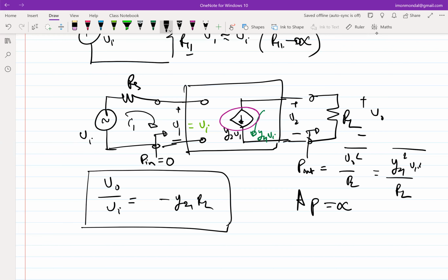So when I say P in equal to 0, what I mean is that the power drawn from the visible input source is 0, but there is a battery which is invisible, right? You are drawing power from there, and only from there are you getting these Y21 terms, right? So the genesis of Y21 is because you have a finite non-zero IV characteristic with certain slopes. In order to generate those IV characteristics, you have to naturally give some I and some V, which means you are burning power. And the power that you are burning will be evident from the IV characteristics at which you have biased your network. That's all. Okay.